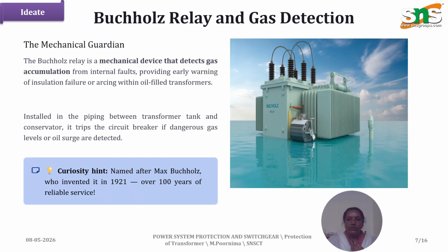Here coming to the Buchholz relay. So we can see the Buchholz relay is a mechanical device that detects gas accumulation from internal faults, providing early warning of insulation failure or arcing in oil-filled transformers. Buchholz relay is an important relay for gas detection.